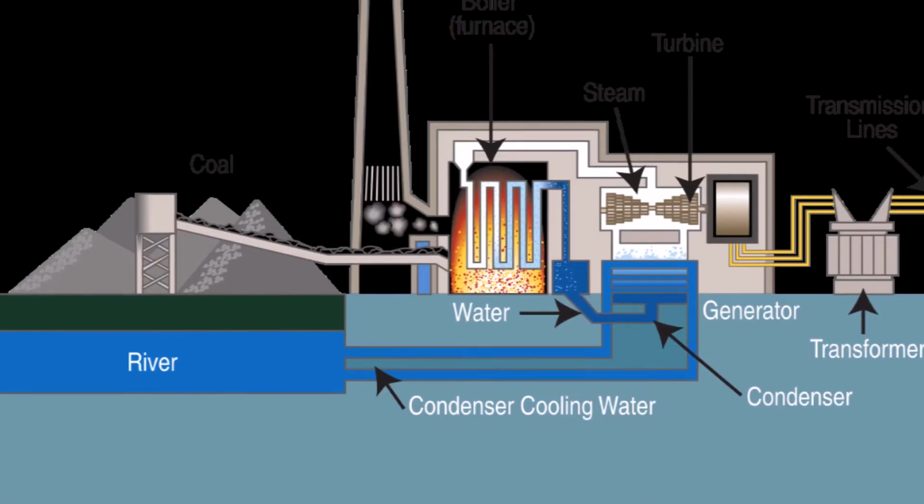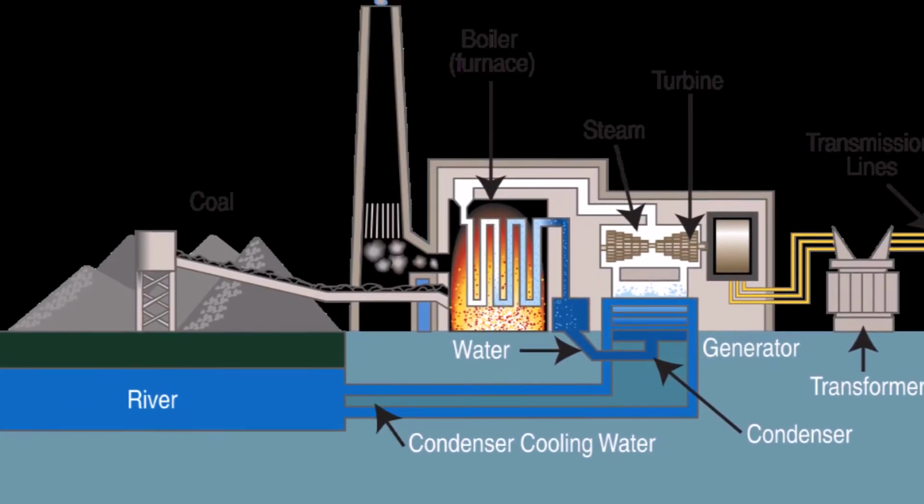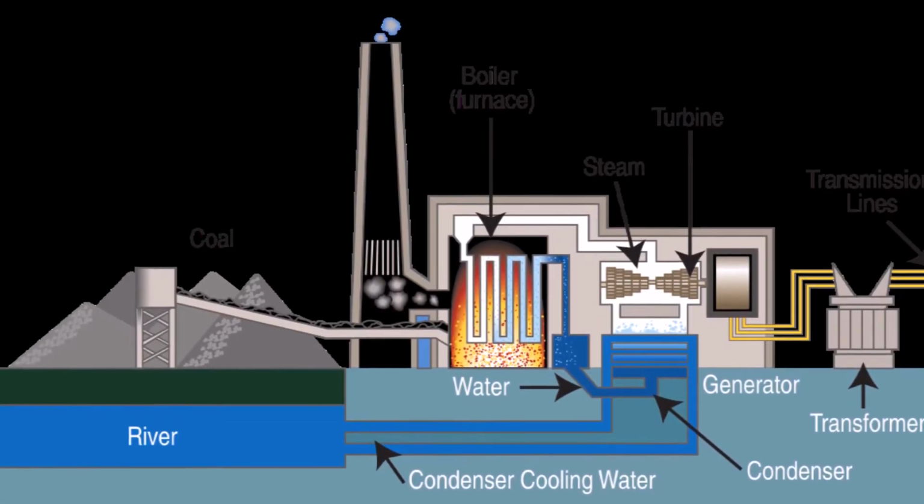The thermal power generation process starts off in the boiler. The boiler consists of mainly three main components, namely the economizer, the steam drum, and the superheater. In the furnace, the pulverized coal is heated rapidly and burned to supply heat energy to the boiler.